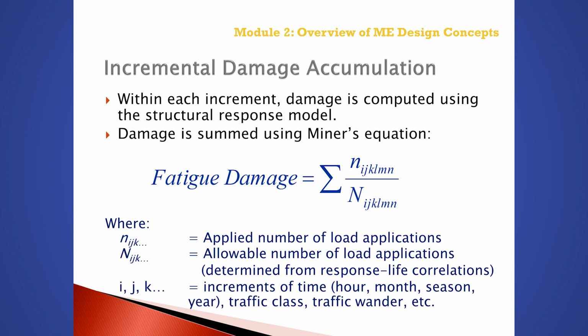Basically, the PMED software breaks the design period into intervals, and the actual and allowable number of load cycles are determined for each interval and site condition. The incremental damage index is calculated for each interval, and then all increments are summed to determine the total damage for predicting distress throughout the design period. The responses for each distress type and material are presented in the next segment of this module.